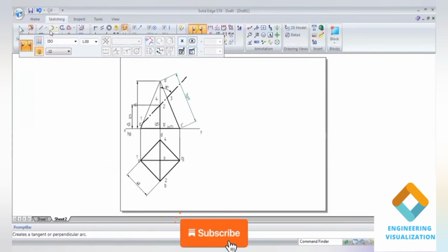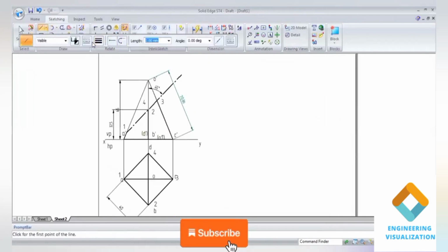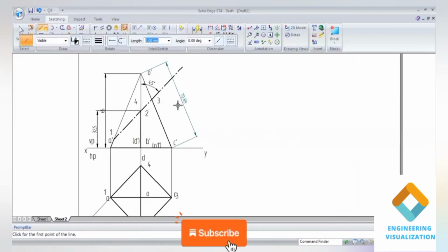Now using this slanted length we will construct the development of it. Same length we'll be drawing a line. Now we need to transfer all these cut points on the slanted length. 1 and 4. This is an important step, guys.